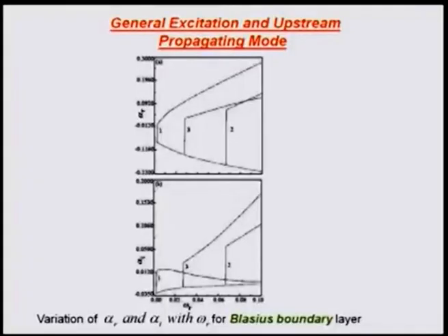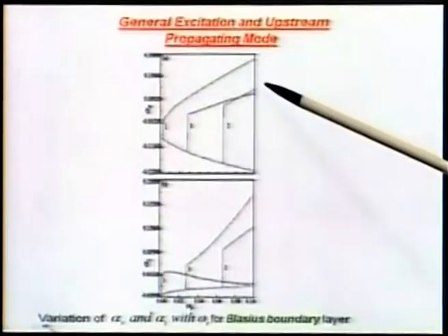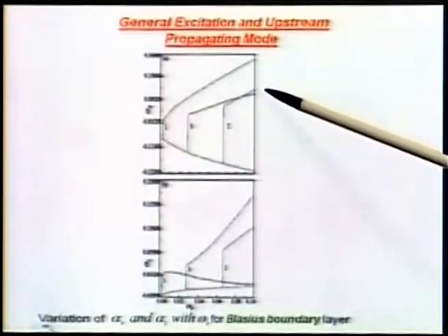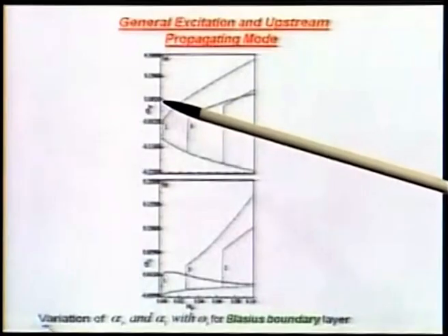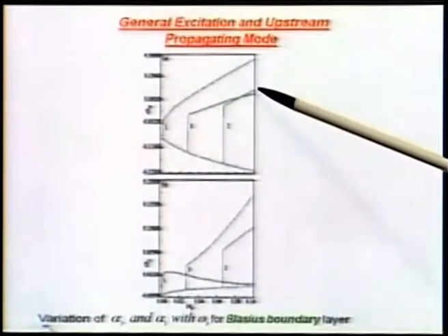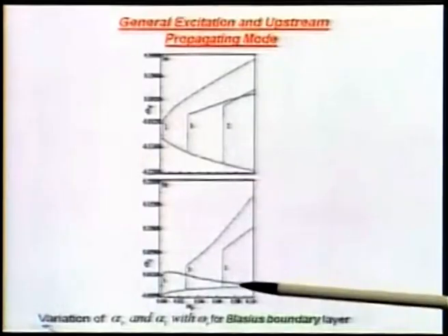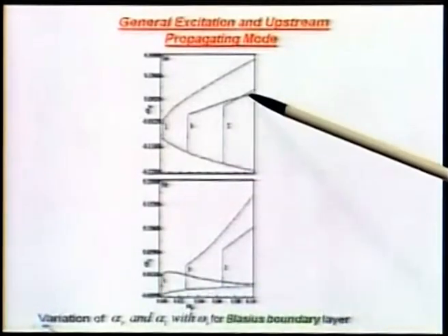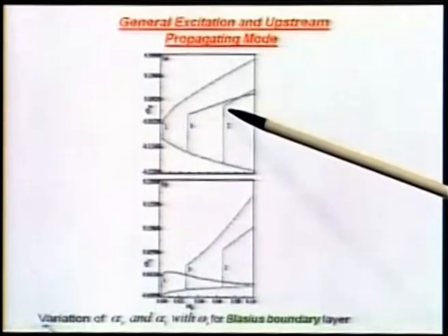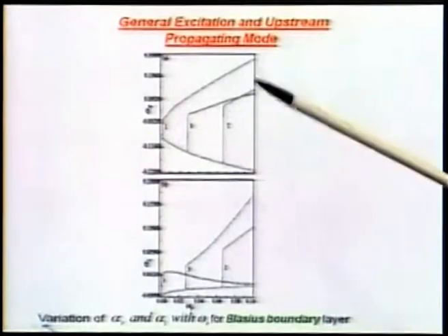Now, if I start from that circular frequency of omega naught equal to 0.1 and start reducing the circular frequency, then one by one the eigenvalues disappear. For example, this mode 2 that we talk about, this is an alpha r positive value. When we keep reducing omega, which is plotted along the x axis, it goes down and then all of a sudden the second mode disappears.